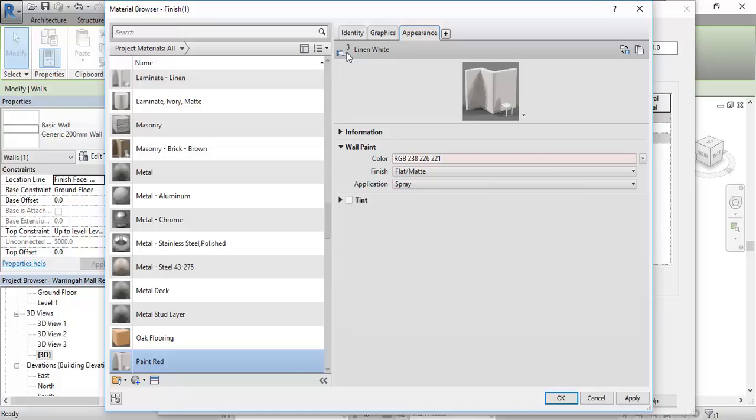If you see a number there, you should normally right-click on the Appearance tab and then either replace or duplicate, because that number is telling you that other materials in the list are linked to this appearance. So if you change this colour without doing this step, other materials are going to change. So just force yourself to remember that, even if you're not sure why. Again, either duplicate or replace. In this case, I just want to copy this material so that I can change it. So I'm going to choose duplicate.